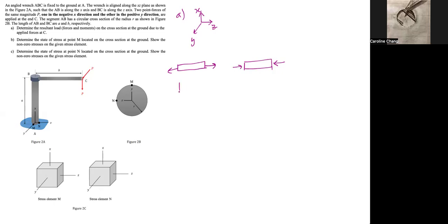In addition, we have to note that if we cut a beam in half, the positive conventions for moment and shear is given by positive shear is pointing down when looking at the cut beam from the left end, and the positive moment is counterclockwise. However, for the right beam, this is not really the case because over here we'll have positive shear pointing up and positive moment being clockwise on this end of the beam. So just keep that in mind.